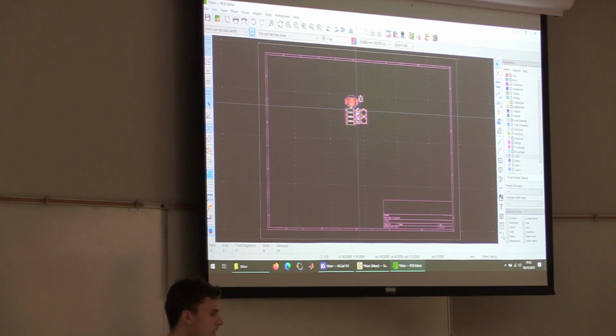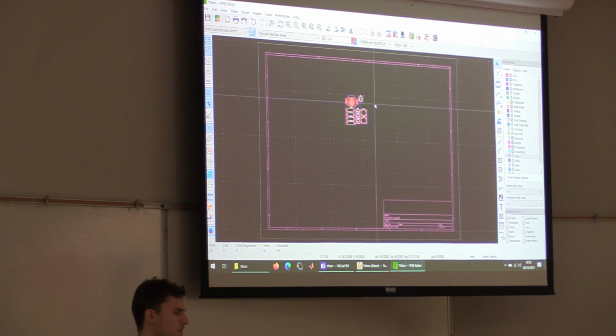So after you close out of that window, it'll sort of just float around with your cursor. Once you hit left click, it'll place them. Normally with larger schematics, you'll have an overwhelming amount of footprints that you need to sort through. Normally I will sort of group footprints based on function, kind of keep them all together, and then as I'm building the board, I will place them as needed.